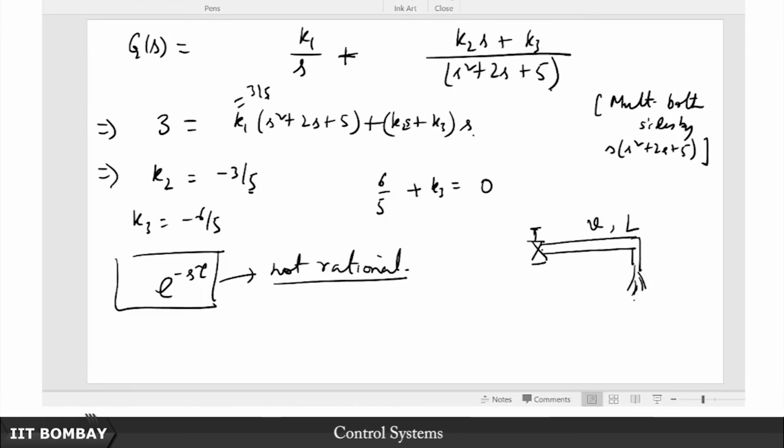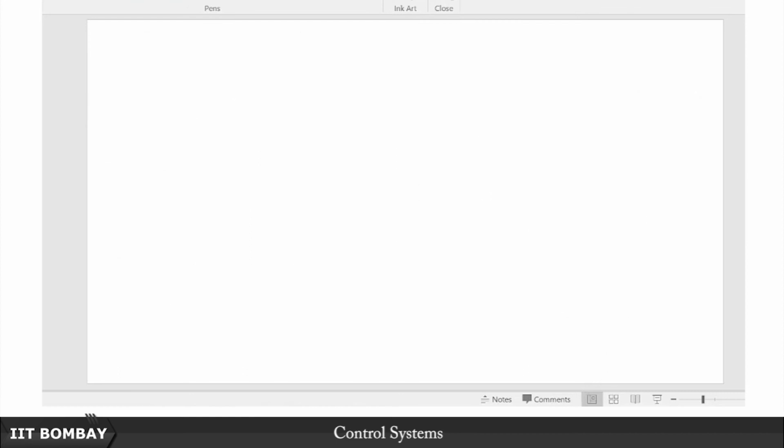The time it takes for the water to flow between the knob being turned on and the water to flow out from here roughly can be estimated. A very rough estimation would be L over v seconds, right. So that is where you might model this as a shift, a time delay of e to the minus L by v s, okay. So this does appear in time delay systems and you will be faced with these. What do you do then? Again, instead of generalizing this, I believe that nothing speaks better than an example. So how will you do this?